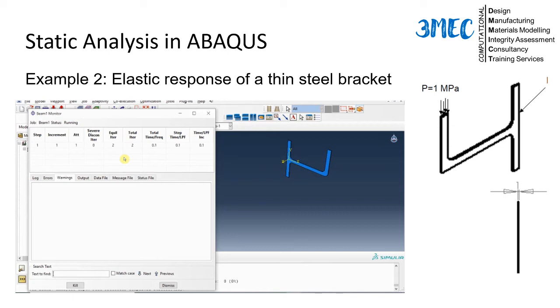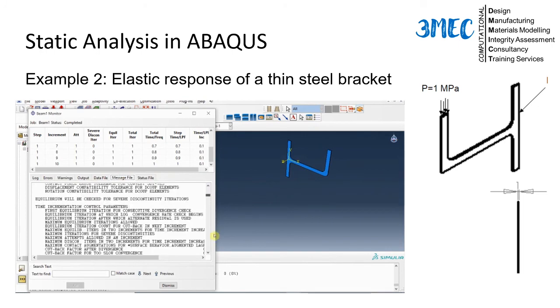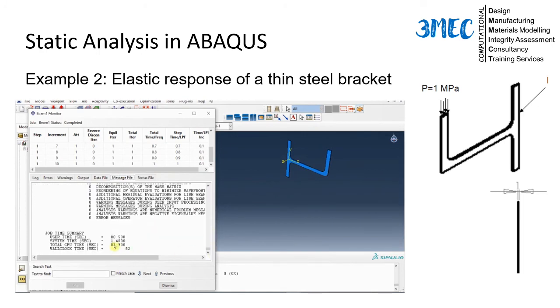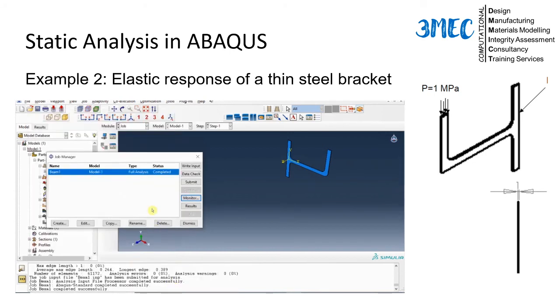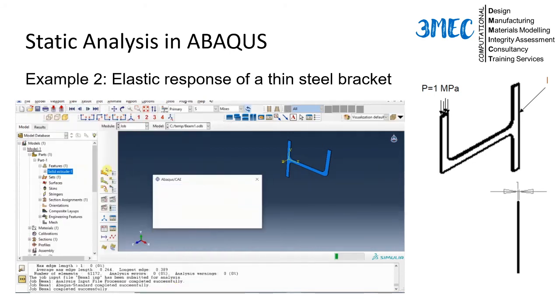Okay, something is there, so it has finished first increment. So you see, same model was solving in few seconds, 10-15 seconds, and as we refined the mesh to find the best solution, my solution time has increased drastically, computational time has increased drastically. So again, decide on your own what is the best purpose. Again, still it was within 1 minute time, but sometimes it can go very long. So it's around 81 seconds, as you can see here, CPU time. So more 1.5 minutes or so.